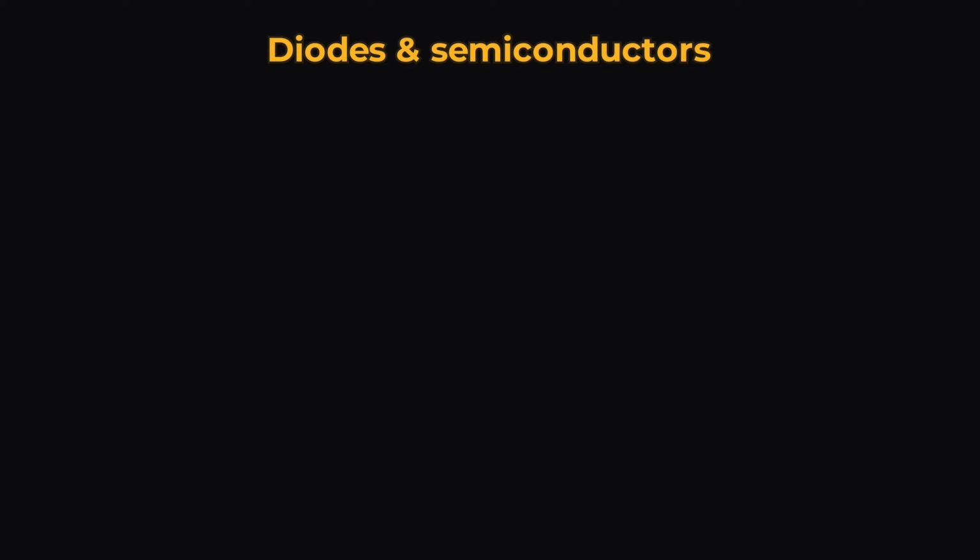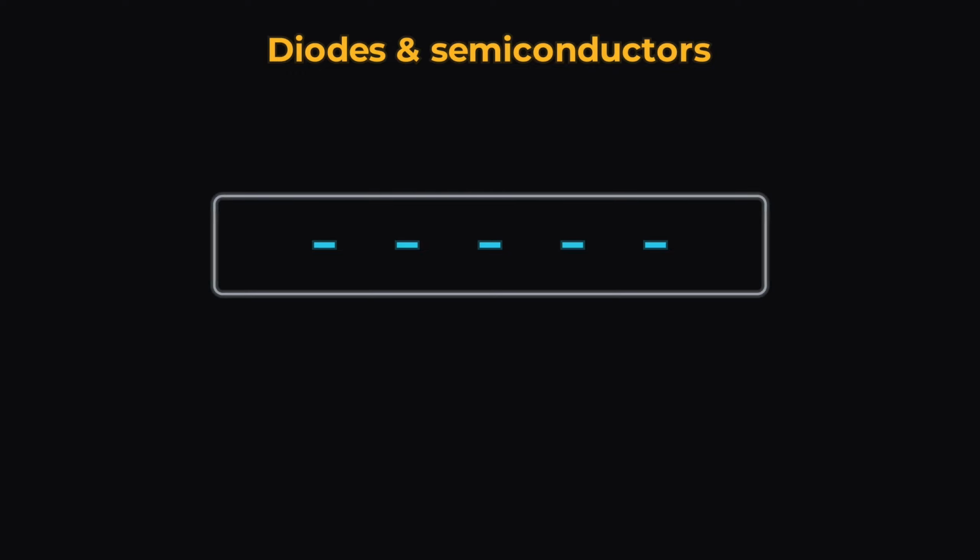One point must be clear before we continue. At room temperature, the dopants are already fully ionized. Donors have given up their extra electron. Acceptors have already captured one. This is true before any junction is formed. A uniformly doped bar of silicon is not yet interesting. It has no built-in field, so it behaves like a resistor. The useful physics begins only when we join two different regions.